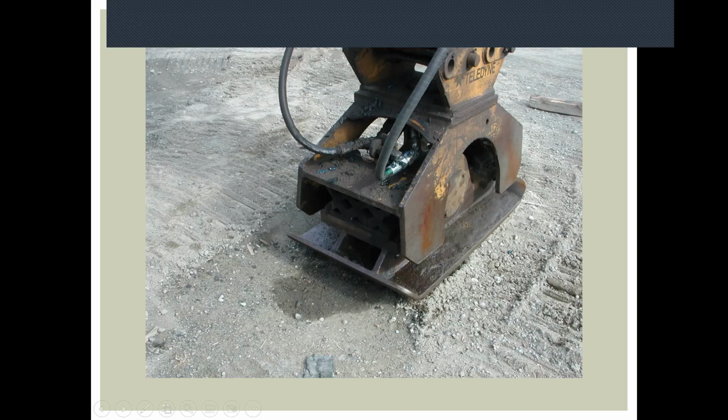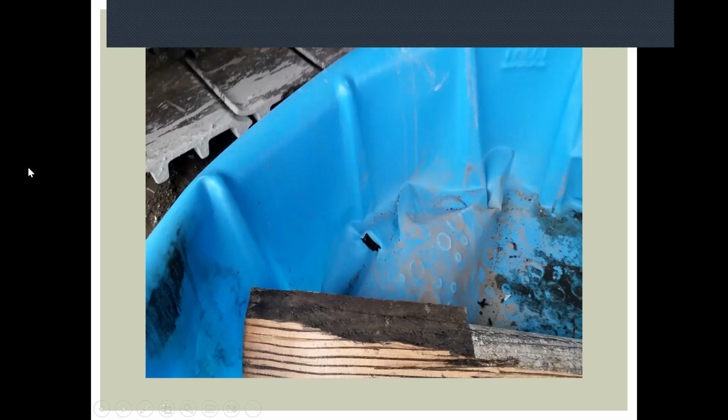Equipment leaks, not just from the engine and hydraulics on the piece of equipment, but also on attachments. So this is a small spill of hydraulic fluid, but these can be put in kiddie pools or some kind of secondary containment when they're not being used. And make sure the secondary containment is workable, actually will contain.